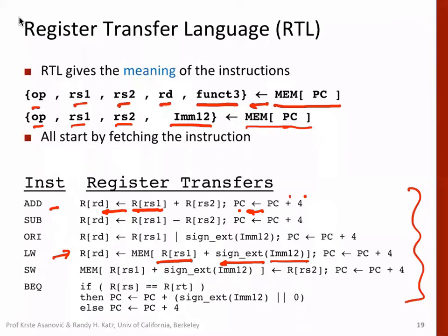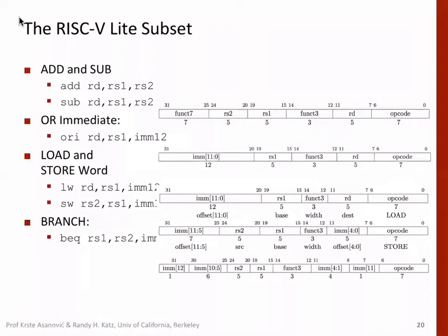Then this becomes the address, and from this address we get the value and store it into register RD, and then change the PC value by 4 to point to the next instruction. So this is very simple. Please go through it, and then you will understand. Otherwise, we'll read it from the book. It's available in all books. Any question?